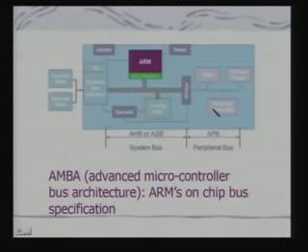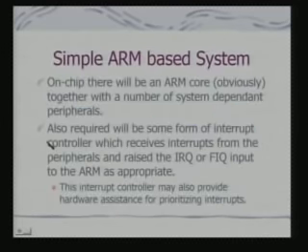On the peripheral bus you have your timer and your interrupt controller, because the interrupt controller will be interfaced with the devices. And this is your arbiter. If there are multiple bus controllers trying to access the bus, I have to do an arbitration, so I need an arbiter block. This is a very broad overview of the AMBA bus.